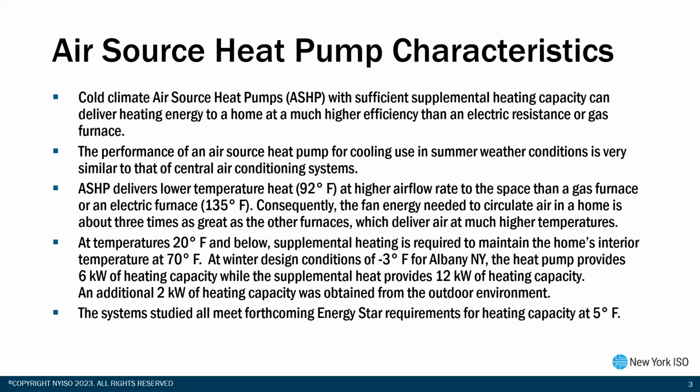So cold climate heat pumps is where the focus is, not heat pumps that you might purchase for your summer and then whatever capacity is left, provide some heat. No, if we're going to meet the climate goals that are set by state agencies or the federal government, we've got to have cold climate heat pumps in New York. And so we've looked at their performance characteristics. They do provide lower temperature heat than a gas furnace. You do need to provide more air handling.